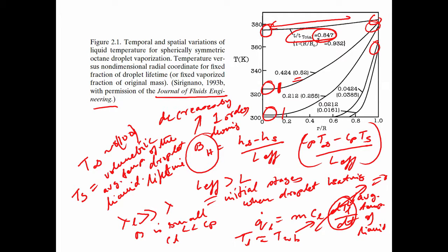So, we have established here when we actually require solving for the temperature field within: we need to solve it for these cases where there is a strong temperature gradient, as you can see, it is not negligible and it persists for quite a bit of the droplet lifetime. In that case, you have to solve this and link it to the outer gas flow field via the interface conditions. So, that is very important.